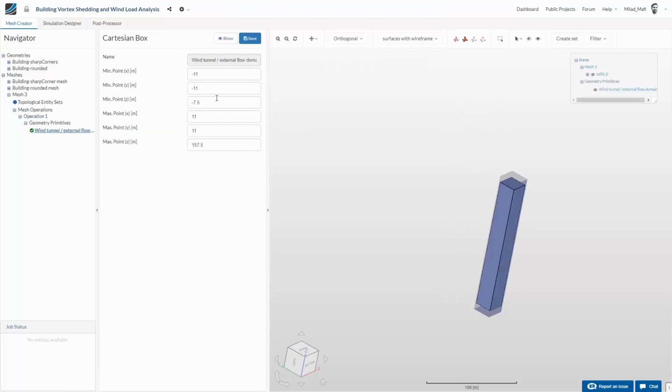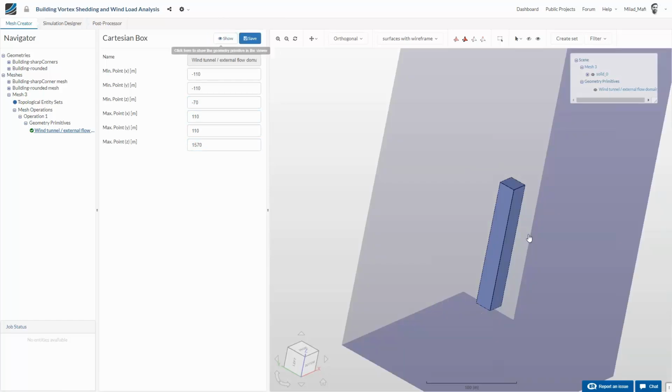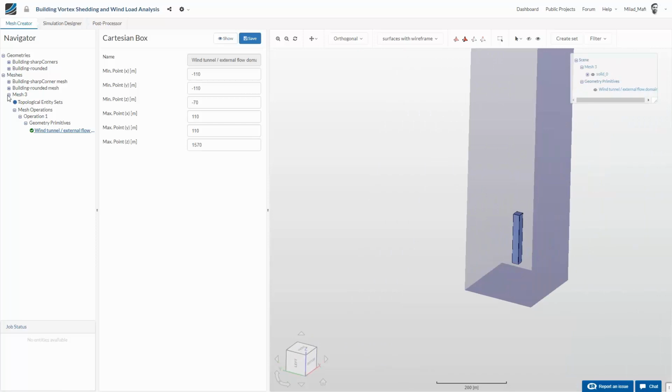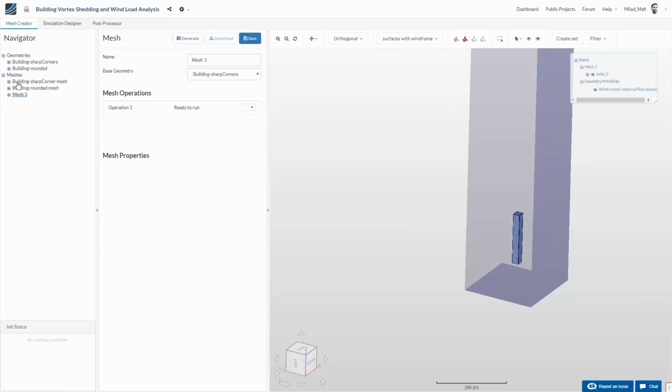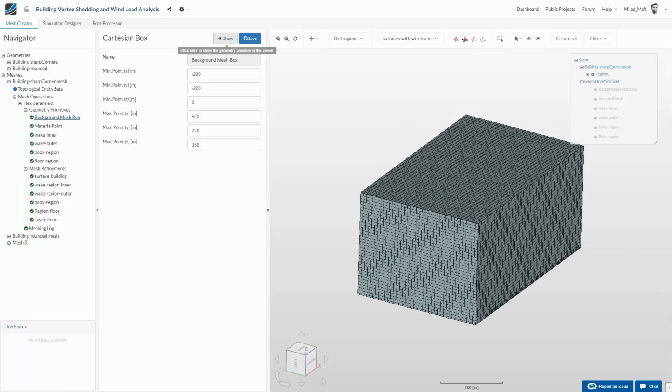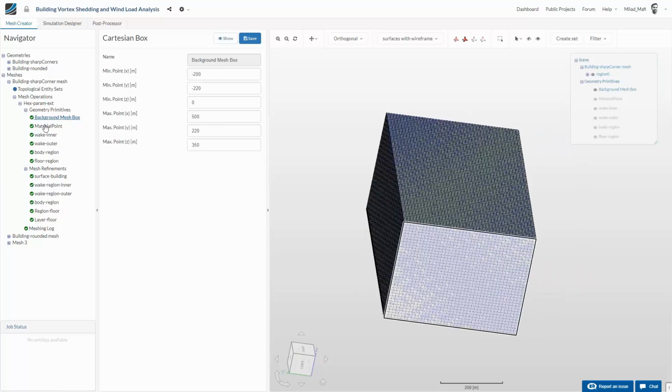So this would be much too small, and we can make it a little bit larger. You can adapt it and bring it to the right size, but we can also have full control over the meshing settings. Then we define this base mesh size, but also refinement regions.